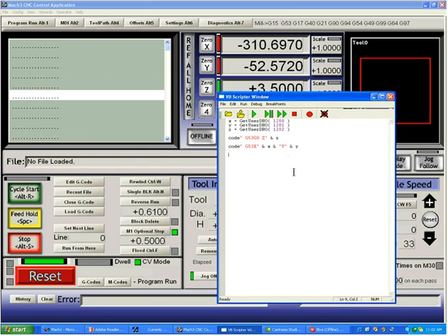Now, let's say at that point we've moved our tool back to a machine coordinate of where we wish to change our tools. We could do other jobs such as zero those controls. So we can type set DRO 0, 0. This is a Mach 3 command which will set the X DRO to whatever number you put in, and it does that by changing the fixture offset coordinates, or it's the same as pushing a 0 button. We can then say set DRO